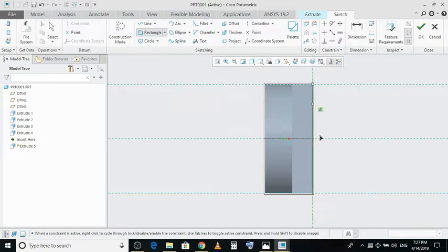You see, it is able to catch. Otherwise, in some cases, you don't need this in Creo 5. It automatically catches the edge, the vertex. But if you're using an older version, it is not able to catch the vertex. So it's better you give a reference line.